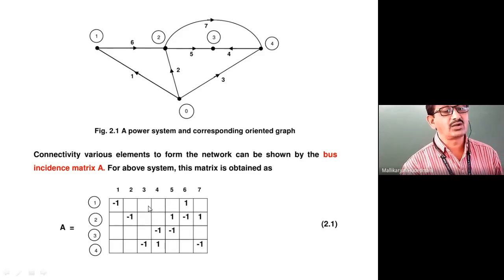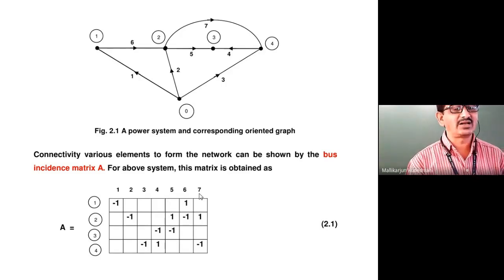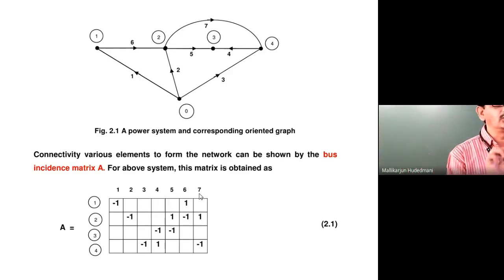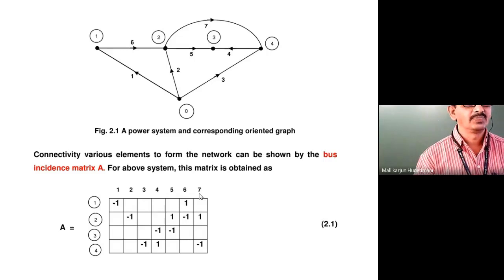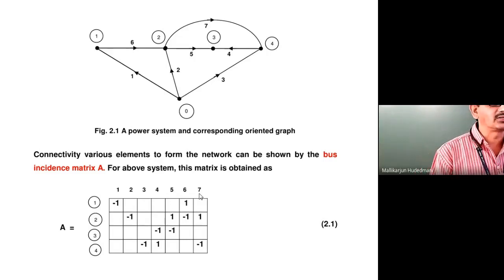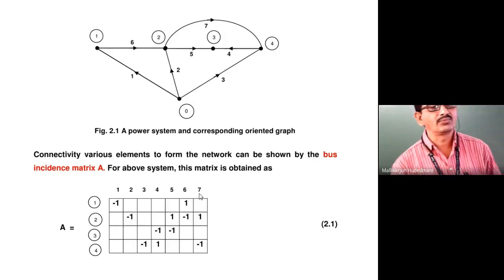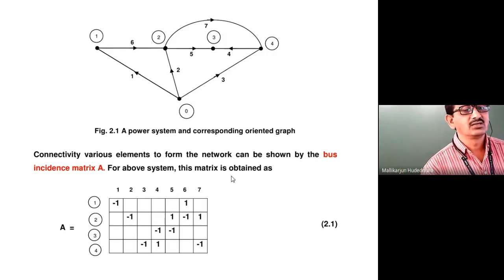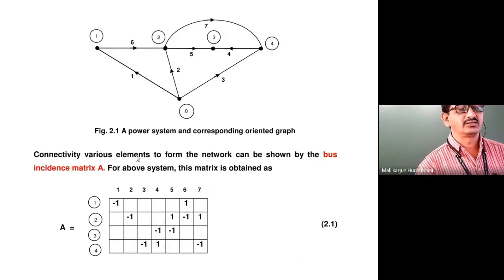Means A matrix which I would write. Directly we wrote the reduced incidence matrix. The work related to the 0th bus, the reference bus, is not at all done. So hence it is called one step advance. Otherwise, if I account for the 0th bus also, bus number 0, it becomes a full incidence matrix. From that, I have to eliminate the representation of the reference bus, then it becomes the reduced incidence matrix. So this was what we wanted to interact.